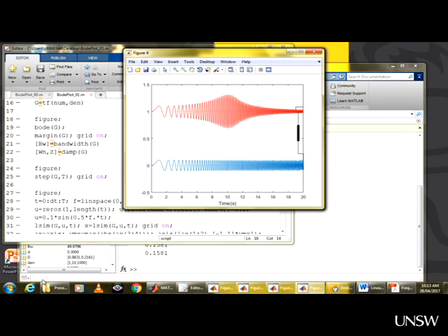What we see here in this simulation is a vehicle suspension system. Sometimes we go over the road surface, which is a kind of sinusoidal surface, and this surface contains different frequencies. The response of the mass-spring-damper system is a function of the frequency. For different frequencies, you feel that your vehicle is moving at a high amplitude or a lower amplitude. So what are the details of this mass-spring-damper or suspension system? Let's take a look.